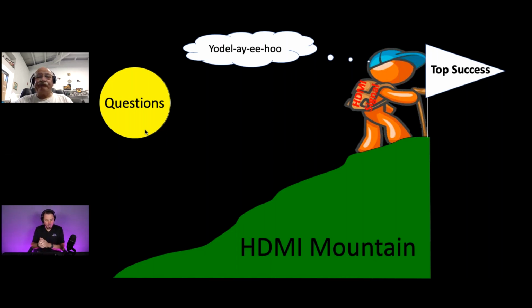When a user changes the HDMI 2.0 parameters from standard to enhanced, the EDID for the maximum pixel clock jumps from 300 to 600 megahertz. Why doesn't HDMI always operate at maximum? Some users may forget to switch to the higher operating mode, for instance, and will only get 422 instead of 444. Is 600 megahertz more power hungry than 300 megahertz? And are there any considerations to operate at 300 megahertz in standard settings? So it sounds like there's a few questions in there. Do you have any initial thoughts? Maybe we can break down the many questions into one individual question.